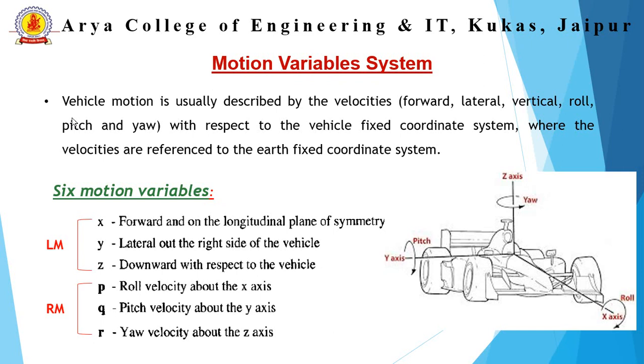and is termed rolling. Then if we are accelerating or braking, the nose of the vehicle will lean forward in the case of braking and lift upward in the case of acceleration. This type of rotation about the y-axis is termed pitching.